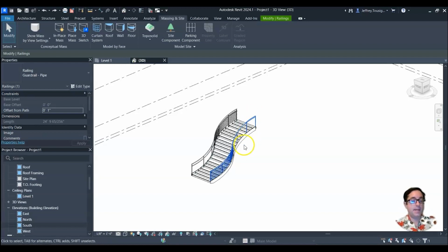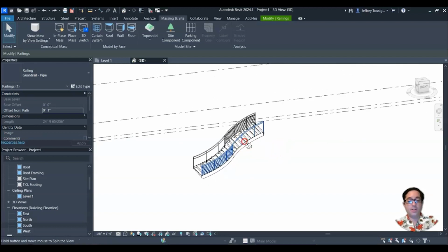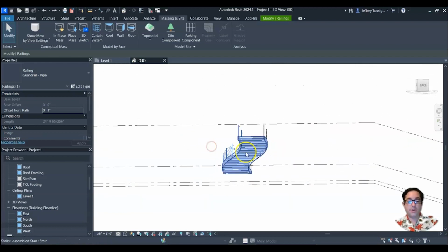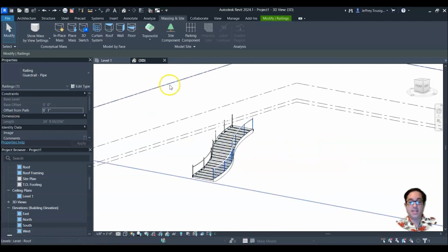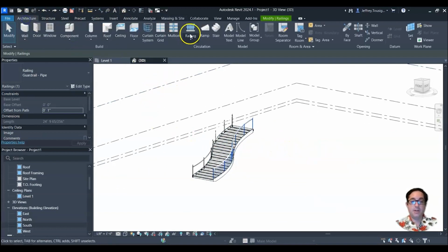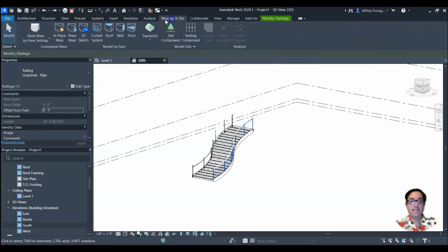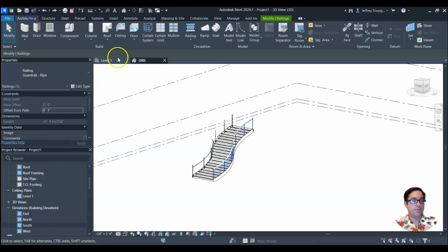If you can't get the form under your stringer or under your stairs or along your railings doing exactly what you want, instead of trying to fight the options that the stair tool is affording you, maybe look into the things that massing in place and creating custom families and adding in walls and using other tools in Revit can help out as well.